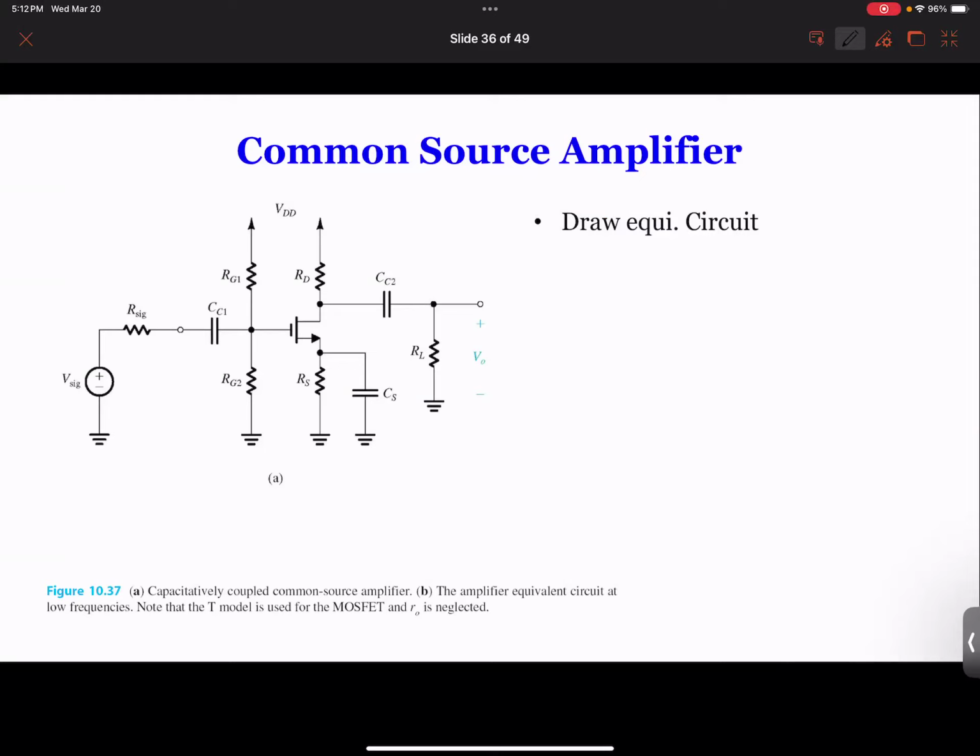And previously, we already know the high frequency response is because of the intrinsic parameters of the device, like CGS, CGD, or CCE, CB, CBC, and so on. Those impact the frequencies, which means they impact the performance of the device at a high frequency.